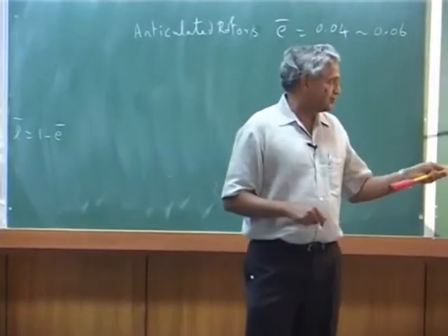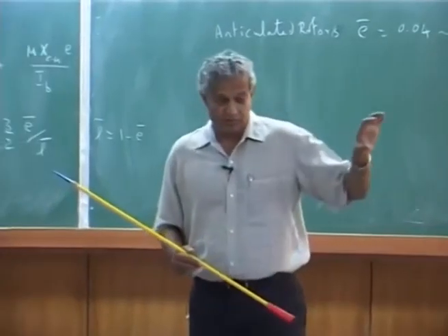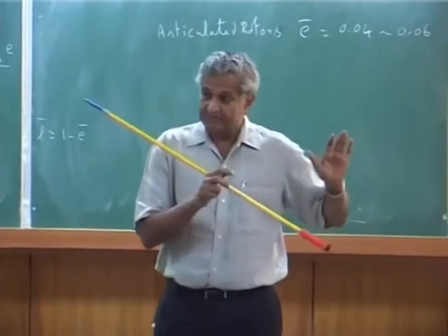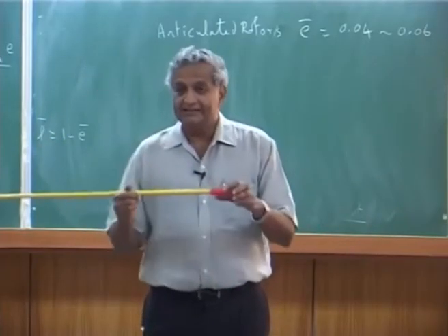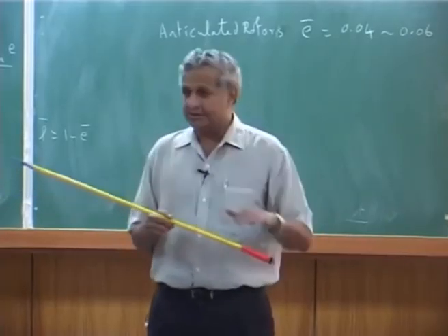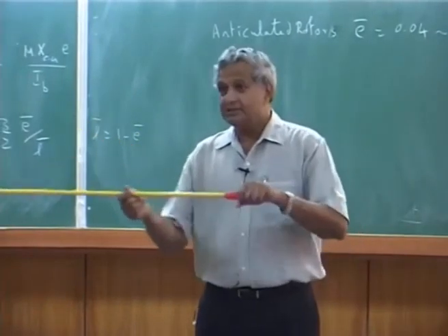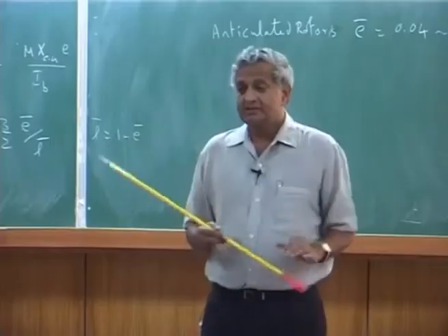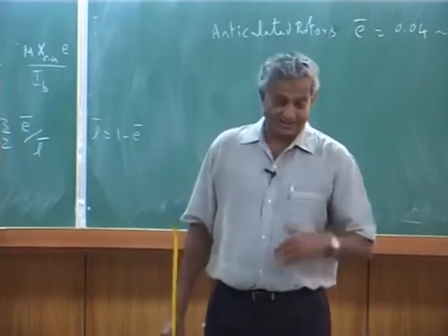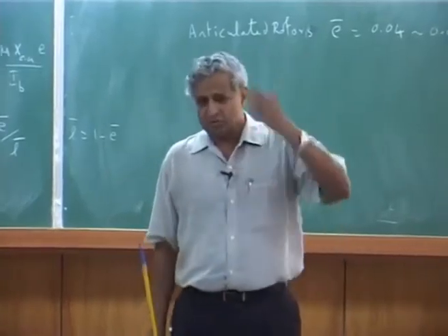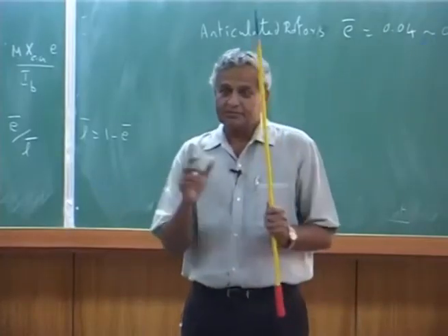On the other hand, if you go to soft in plane, yes, but you have a problem of ground resonance. But to solve that problem, you have to develop coupled fuselage lag dynamics. That is the dominant thing, coupling. That is, pitch or roll motion of the helicopter will couple with the lead lag motion, and then the whole helicopter will go unstable. That is called ground resonance. It happens even before it takes off from the ground, but you also have air resonance. So, these are the problems.